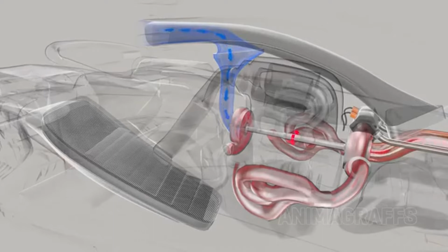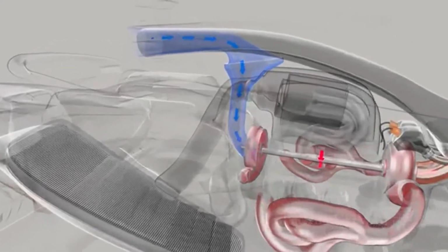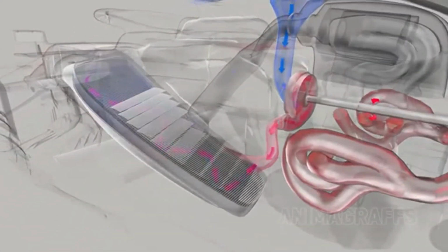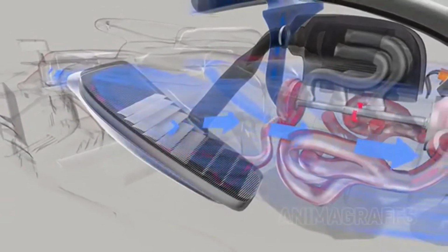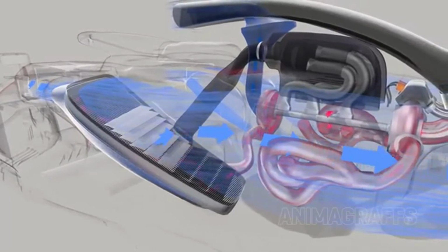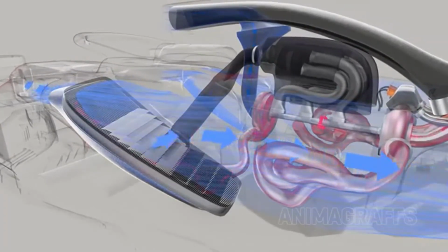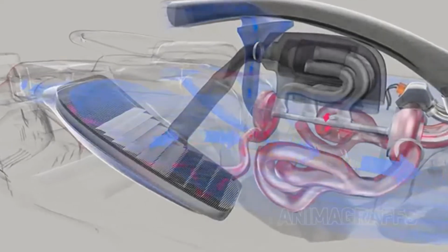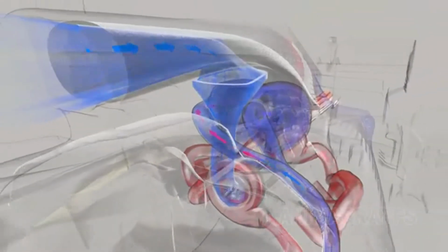The compressor draws air in through an intake duct mounted in the roll hoop above and behind the driver's head. Hot air leaves the compressor towards the intercooler. Side pod air rushes by the intercooler's tubes and fins, cooling the compressor air inside. The now cooled air passes through the special split ducting that feeds separate intake plenums.